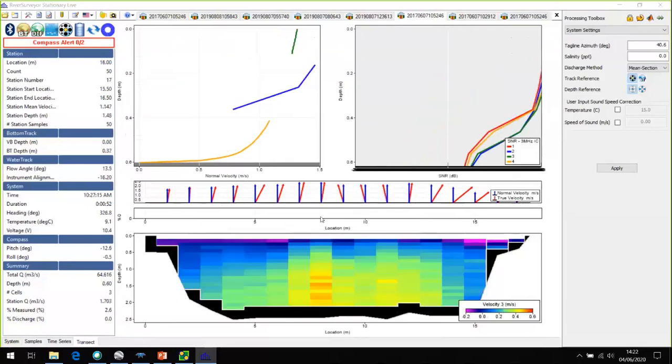Automatic. There we go. So we've got some quite horrible vertical velocities down here. And you've got to ask yourself, why have you got vertical velocities of nearly half a metre a second down near the bed? This just doesn't make any sense whatsoever. That's just wrong. But it's wrong because the two cells are not in the same place when you draw it up. So we got lots of bits of paper and drew them up.